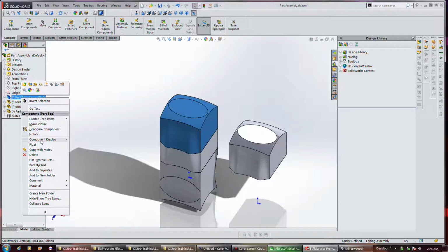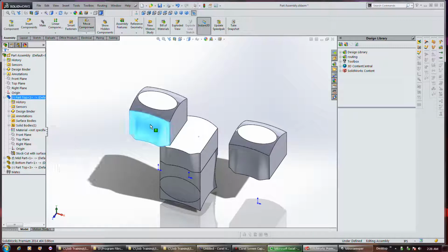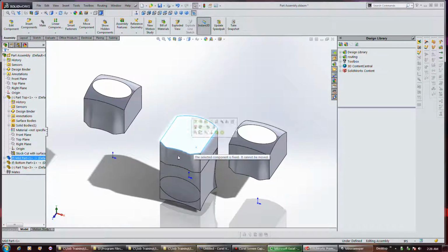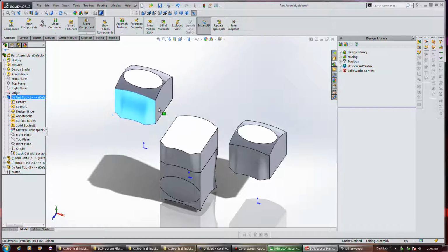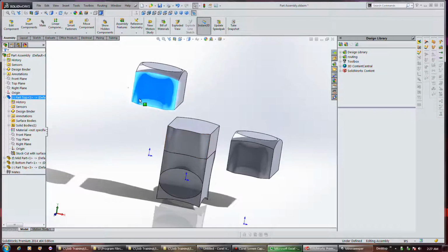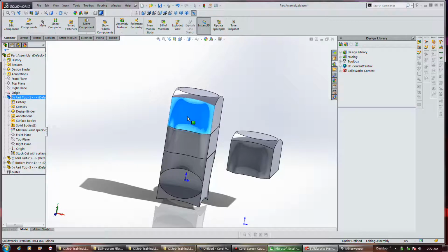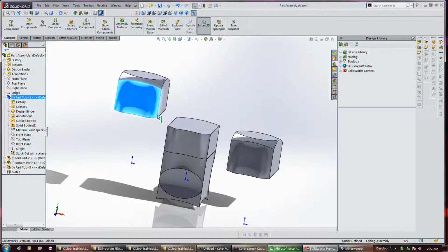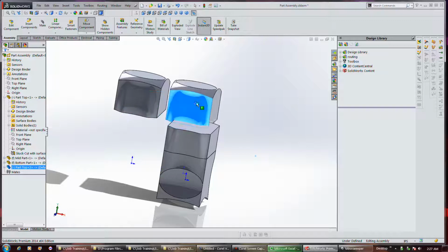But you can click on it and hit float, and that'll make a part so that it can move again. So these are still fixed, but I could float them as well. That's why I couldn't move anything, even though we put these in here. But you can see, since I have the origins turned on, that the parts did have a coincident origin, so they all have the same origin point. If I had put these parts in that other assembly referencing that origin, they would all snap together the same way because they have the same origin point. So even this will have the same origin point because it's just a copy.